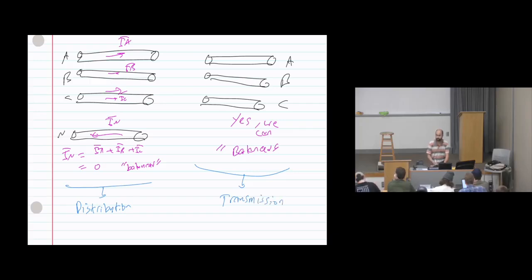And actually, the transmission cost is much higher than the distribution, especially with regard to the neutral, because in the distribution, basically it will go for a few miles. For example, inside Auburn, look at the closest electrical substation, which we have close to the stadium, and it's not too far. Or we have one at Dean Road, or one at Sanford, whatever. So we have multiple here, and it will go for a few miles at max. It will not go for very large distances. So as a result, we can put in a neutral without any problems.